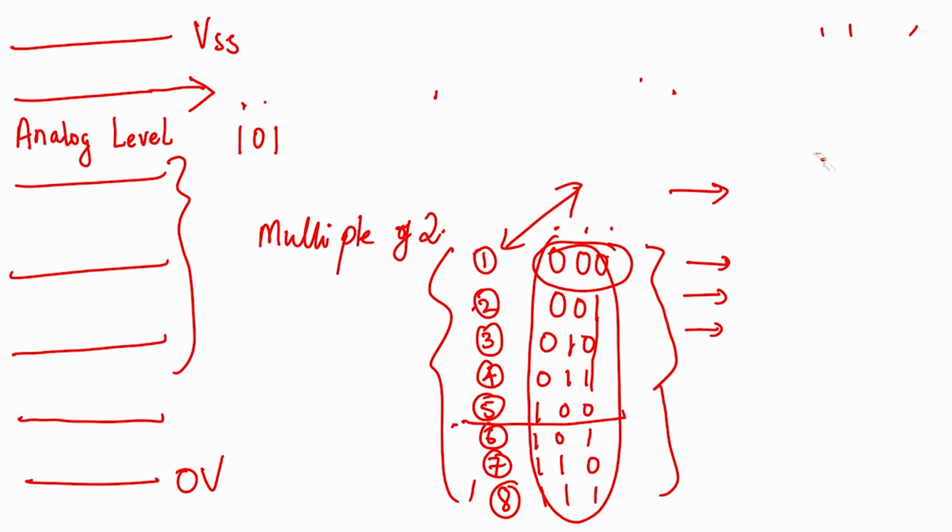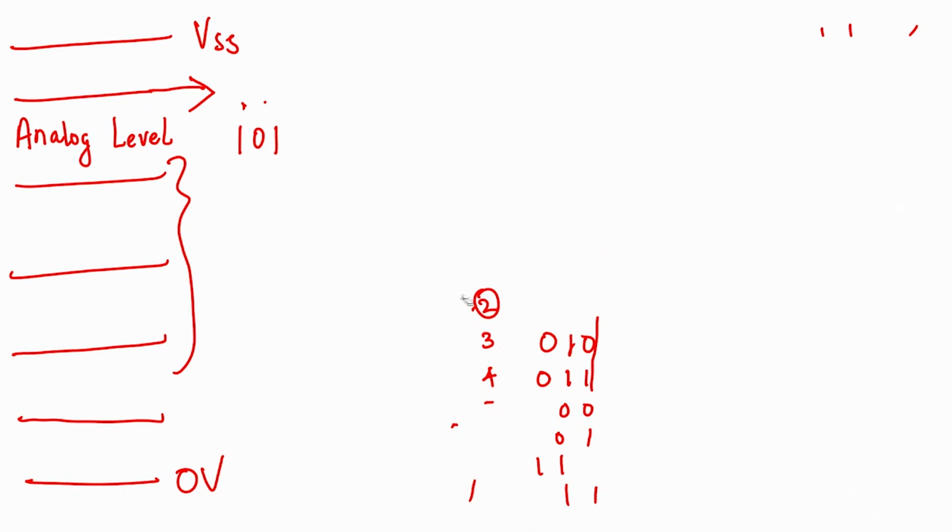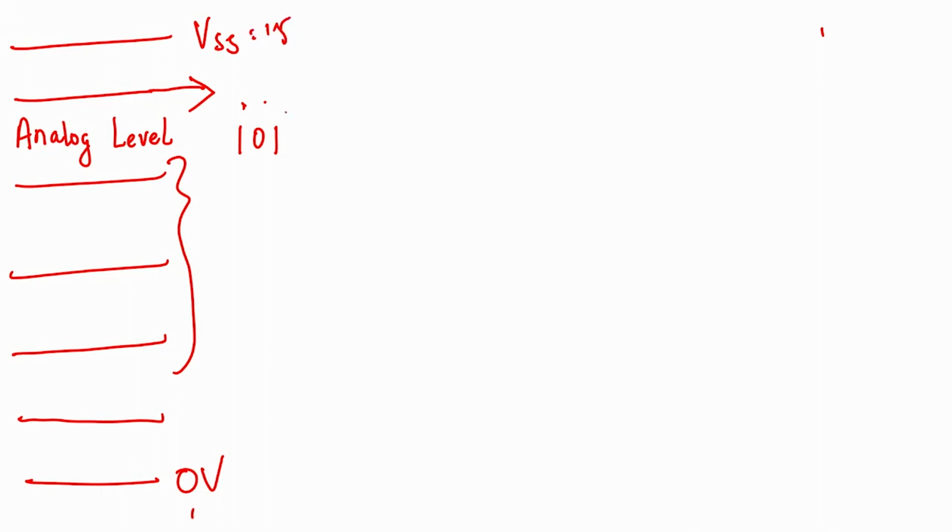So what have we done now? We have discretized your analog signal into a series of digital bits and then set their values, like what defines them at what point. So what have we necessarily done? We have necessarily done what is called analog to digital conversion. So what this means is that we have 0 to, let us say, 15 volt. Let us stick with 3 bits now. That means we will have 8 levels, as we discussed.